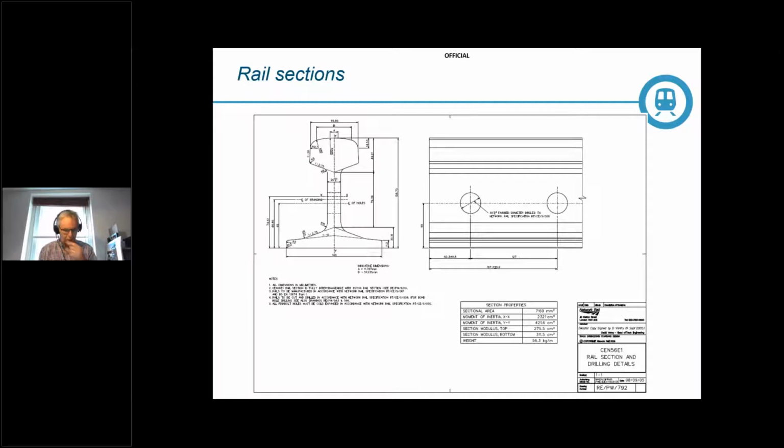Rail has to withstand rolling contact to the head, which will also result in wear and can result in rolling contact fatigue. So a rail needs to be wear resistant, be resistant to abrasion, be strong enough to support and guide trains while spanning between the sleepers, be resistant to impact loading, for example, from things like wheel flats and out of round wheels. It must allow the application of fastenings to hold it down, and it must allow jointing by mechanical means and by welding.